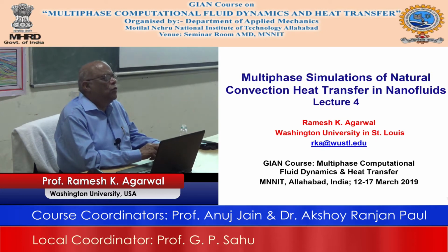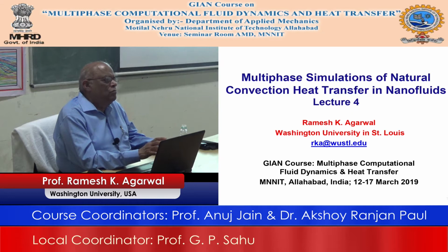So then you can still use a Eulerian method, which is there in the ANSYS. Do not use the discrete element at all, because you will be spending too much time and resources without any gain. Okay. So here we are going to assume that nanofluids are not more than 4% in what I am going to show you.